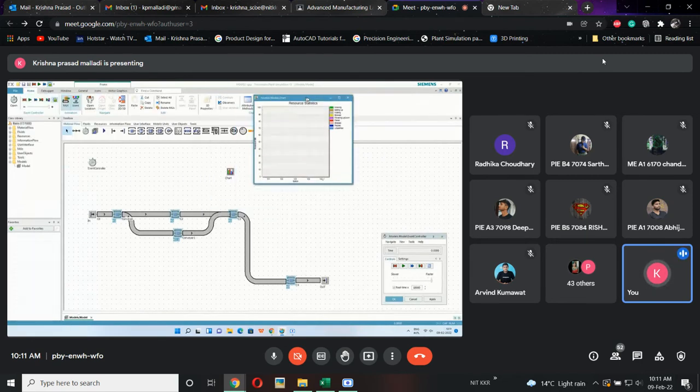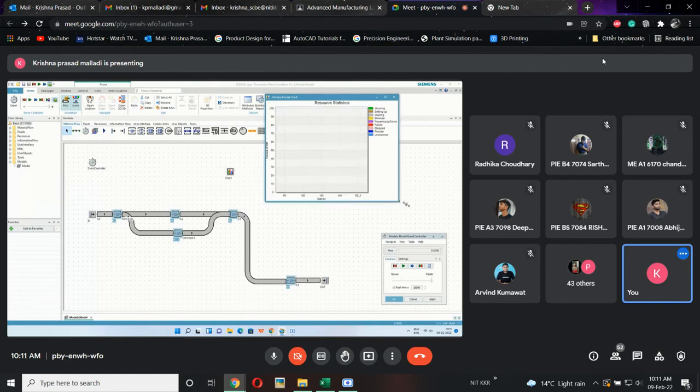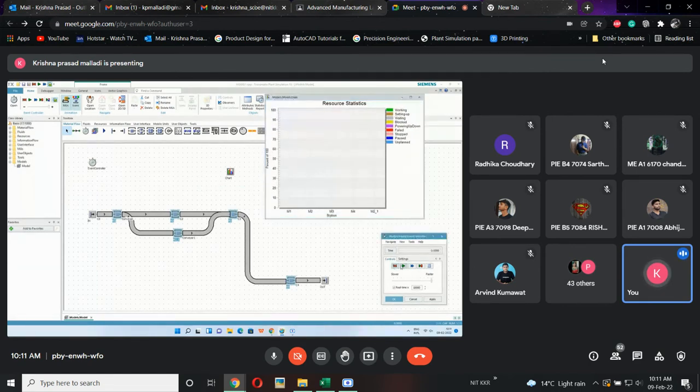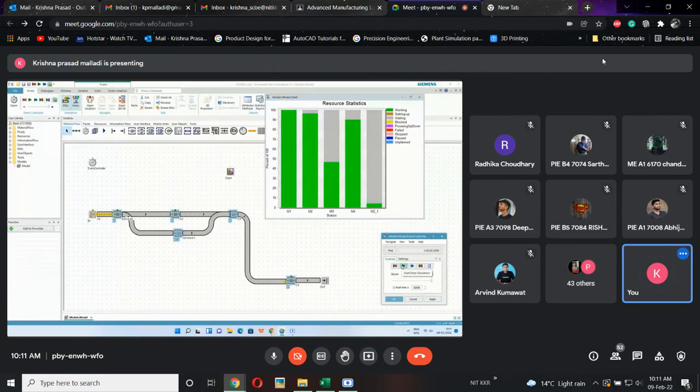Now this is exactly what the chart bar will be. See M1, M2, M3, M4, M5. Now I am resetting the simulation and running it. Now what happened? The waiting part has been decreased. What happened to this M2 dash? It was connected and everything is perfect. But why is M2 dash still having very little usage? Hardly 5% of the process. Why did it happen?